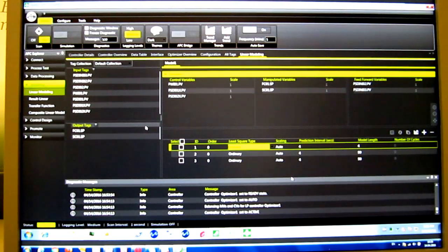Normally, in the first order type of responses in the process, most of the time you use FIR. Each technique is really well documented and mathematically explained, and most of the software from our competitors is doing exactly the same identification techniques. What we can do after this presentation is I can send you the manual of the APC, so you can have a look in more detail there of how to do this. But in essence, this is the software. We'll have an algorithm internally to generate the models for you. All you need to do here is do the pairing, set this configuration up. And once you've done that, then you have